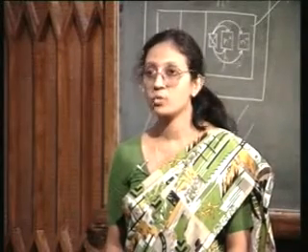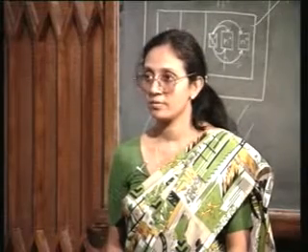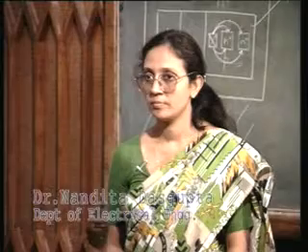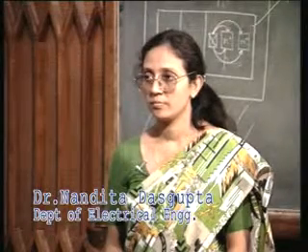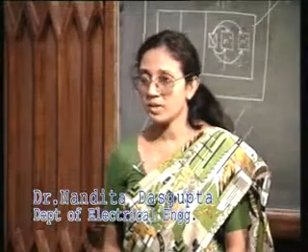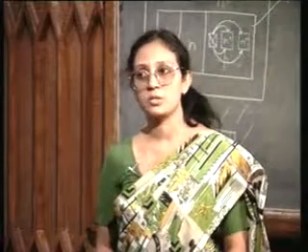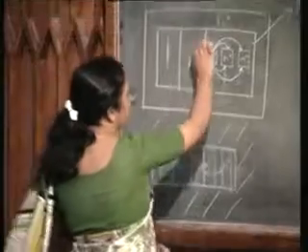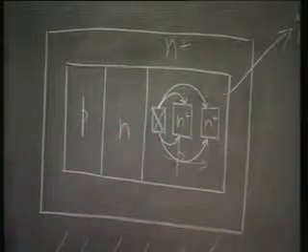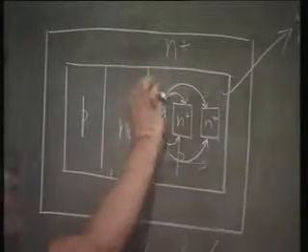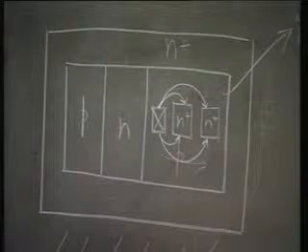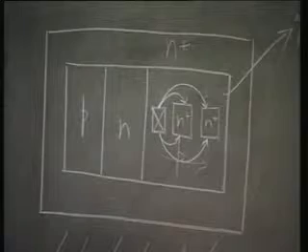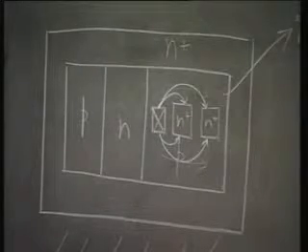So, different fan outs will receive different drives. Okay? So, this is the problem in the oxide isolation case. By removing these rails, which I thought was the unwanted region, by removing these additional P regions, we have indeed saved a lot of space, but in the process we are having unequal drives.